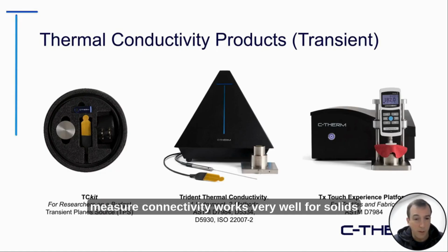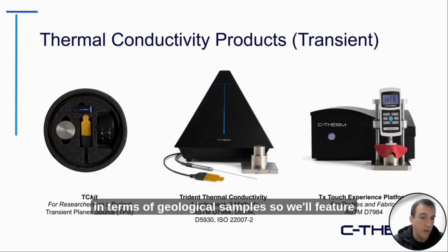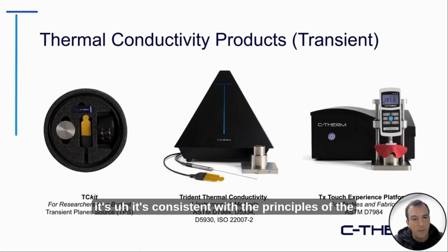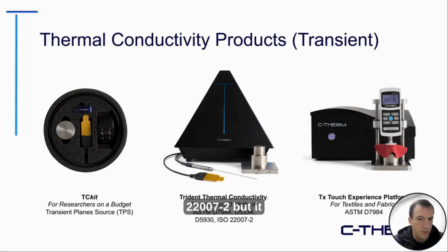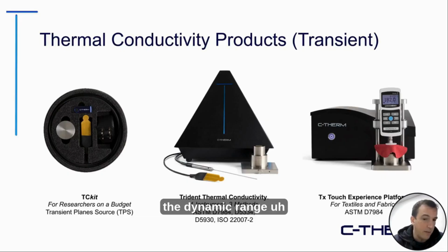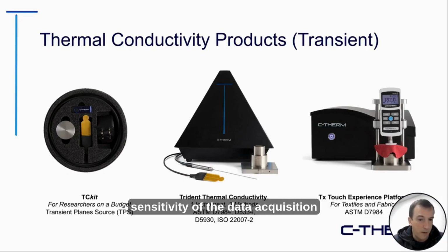It works very well for solids, and particularly the solids like we're going to be testing in terms of geological samples. So we'll feature some of this in today's presentation. Now, this is consistent with the principles of the ISO standard 22007-2, but it doesn't fully meet the standards of that, which require a bridge circuit design that enhances the dynamic range and sensitivity of the data acquisition system.